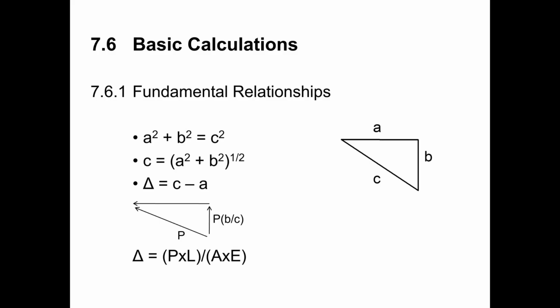All right, and then the last one we got was, when you stress from both ends, are you doing half the force on live end and half the force on dead end, or are you going all the way on both ends? You're going all the way on both ends. Since the ends are connected with each other, in a perfect world, whatever force you put on one end is going to be the force at the other.